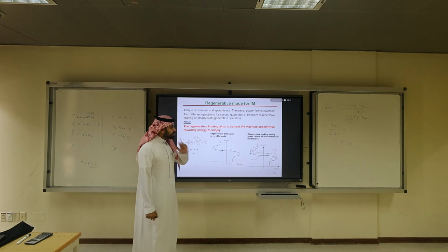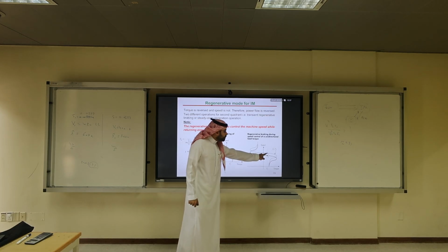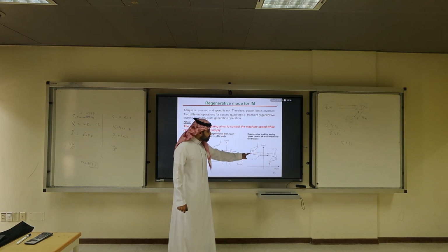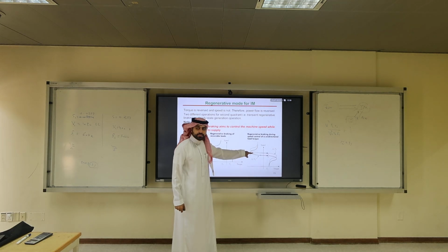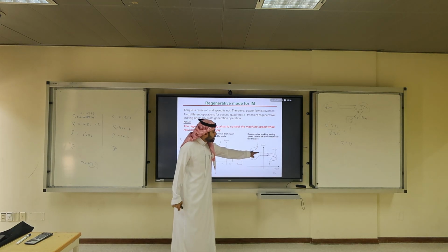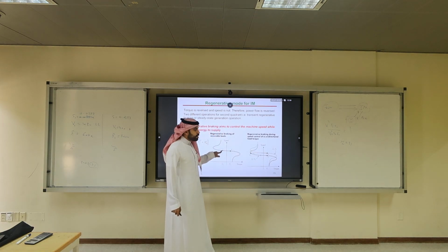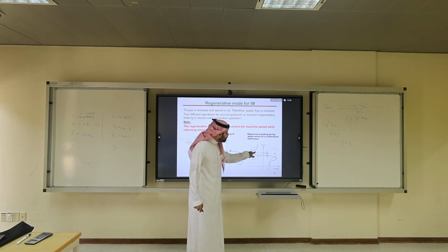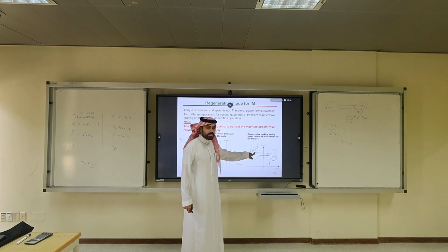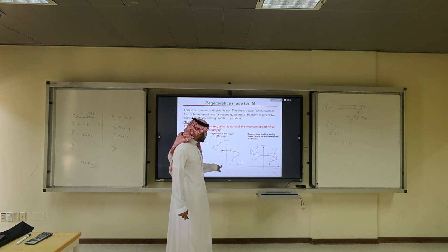What is happening here is you go from point 1 to point 2. Okay? You cannot go to the same point here because you will never ever be able to reach the same curve. Because we have an active load, unidirectional load. Previously you can go on the same curve from 1 to 2, right? For a unidirectional curve, you cannot go to point 2 here. Why? For a simple reason. You cannot have negative torque.